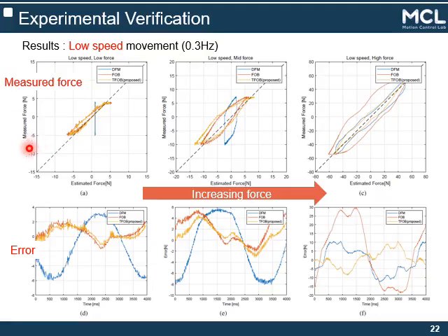So if the plots are linear like this dashed line, it can be said that the force estimation results are as accurate as the external force sensor. The blue line, which is the force estimation by the spring deformation, shows a very poor result, particularly when the forces are small. Meanwhile, the red line, which is the force observer result, shows a bad result when large forces are added. Among these approaches, the TFOB result, which is the orange line, shows the best estimation performance, which can also be verified by checking the error.